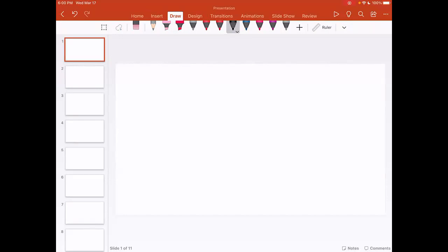So in the last class, we talked about the differences between the spur gear and the helical gear. So the idea in designing a helical gear is we convert this helical gear into an equivalent spur gear.